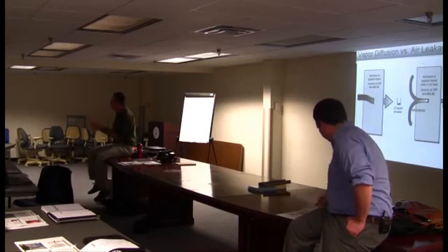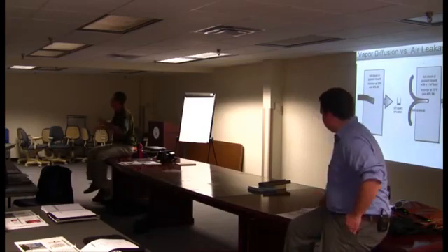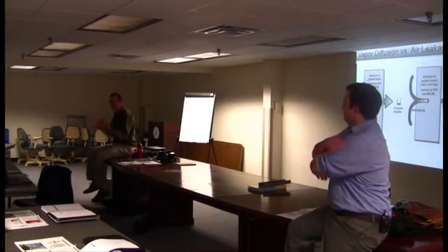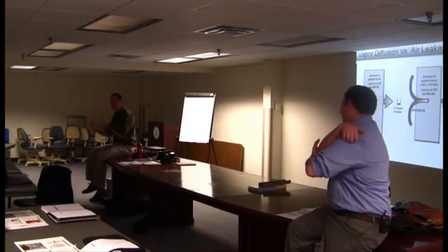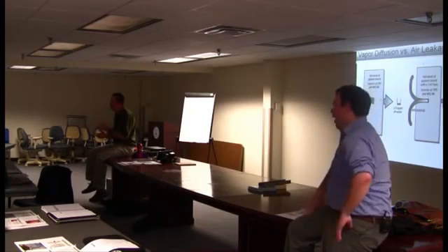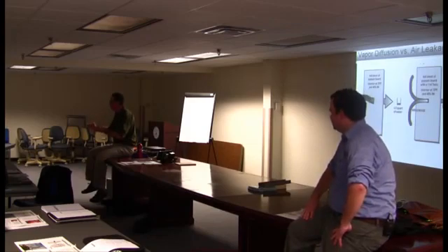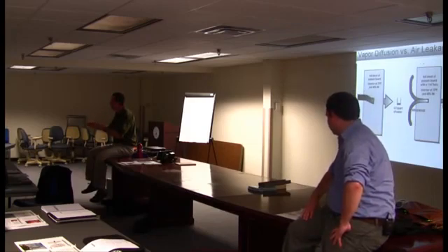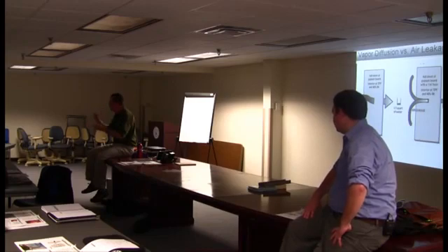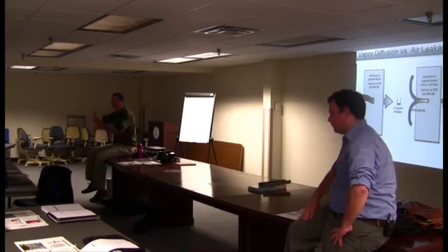Mass walls have a lot of moisture cushion built into them. Heavy walls, concrete, they can take a hit of moisture and probably not rot down, right? But in a steel frame assembly, the only thing that can handle even a remote amount of moisture is probably the gypboard, and not much. So in that assembly, we've got to have a drainage plane behind the synthetic stucco.